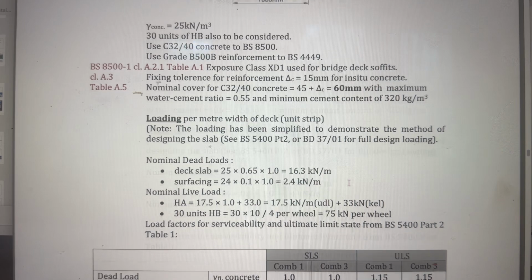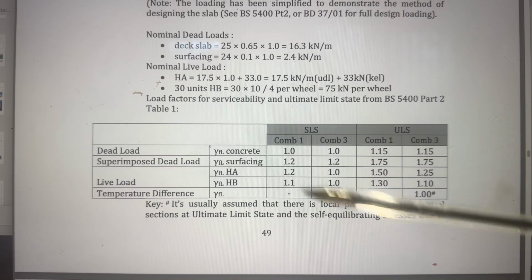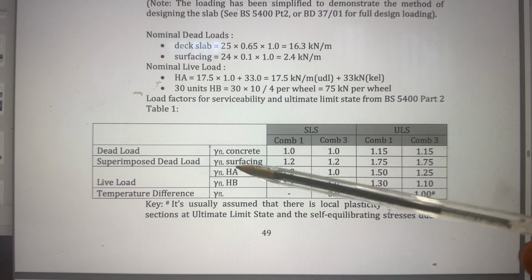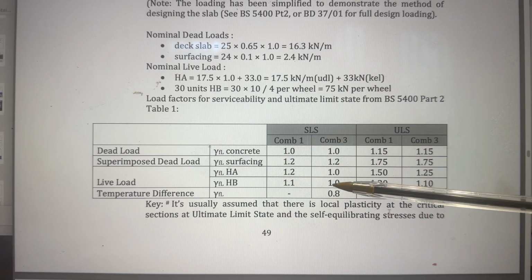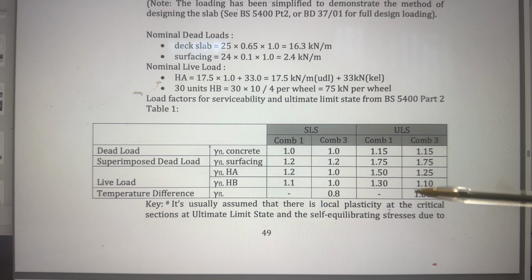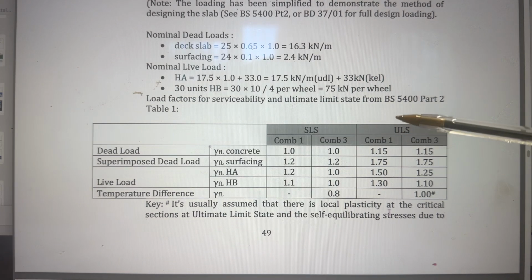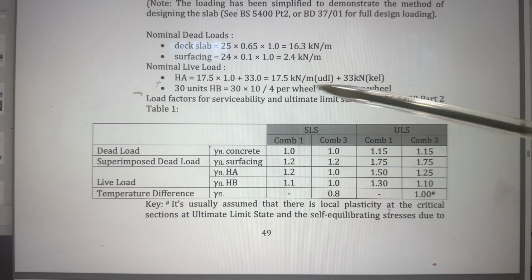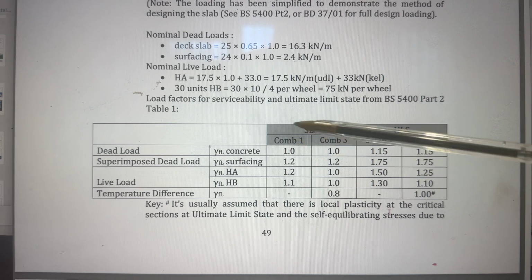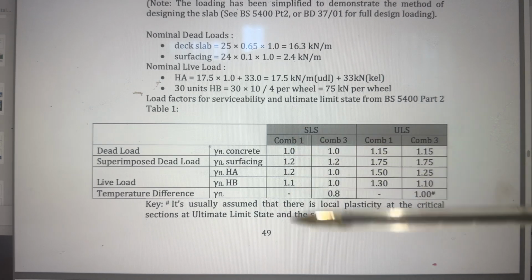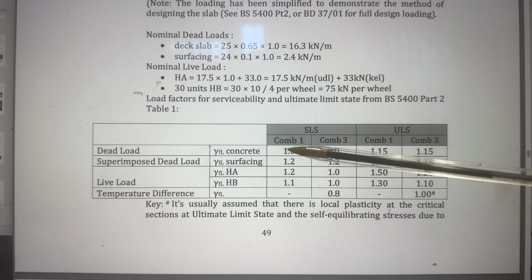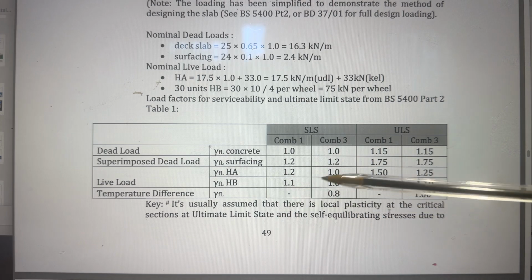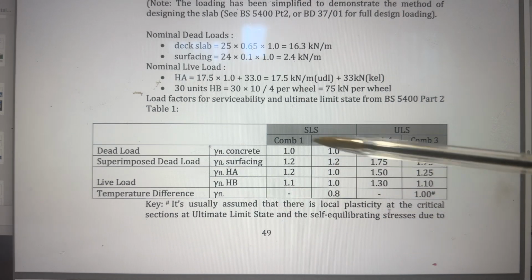Once you calculate, you put those initial calculations, then you multiply them with the appropriate factors of safety. Combination 1 is here, combination 3, combination 1 and combination 3. Remember, in page 38, it discusses the various combinations, and for the purpose of this course and this calculation, we will just look at combination 1. And the concrete factors of safety is provided for you here under combination 1.